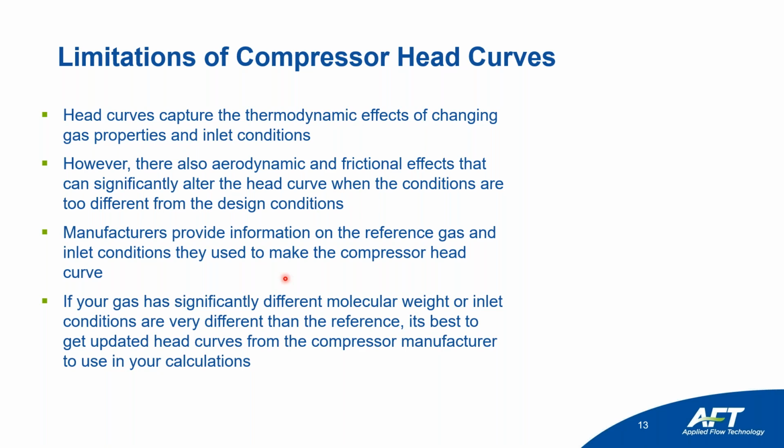So head curves capture the thermodynamic effects of changing properties and inlet conditions, as I mentioned. However, there are also aerodynamic effects of how the gases hit the blades and vanes or impellers within it. And there's also frictional effects. And both of these can significantly alter the head curve when conditions are too different from their design conditions.